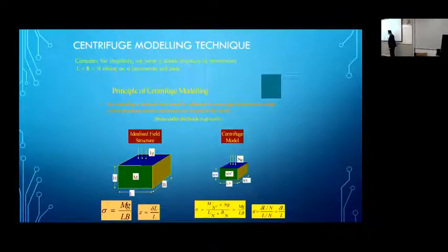So the same vertical pressure will be exerted by this block on the material underneath as that of the big one. Similarly, strains also work out perfectly, that you get change in length over original length as you get underneath the big block. So what we are saying is, if I can apply a scale factor on the buildings, the soil layers, and so on, and reduce them by a factor of n, put them in a centrifuge to increase the gravity by a factor of n, then the little model we built is going to behave exactly like a real building.